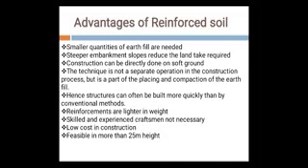Advantages of reinforced soil. Smaller quantities of earth fill are needed. Steeper embankment slopes reduce the land required. Construction can be done directly on soft ground. The technique is not a separate operation in the construction process, but is a part of placing and compaction of the earth fill.